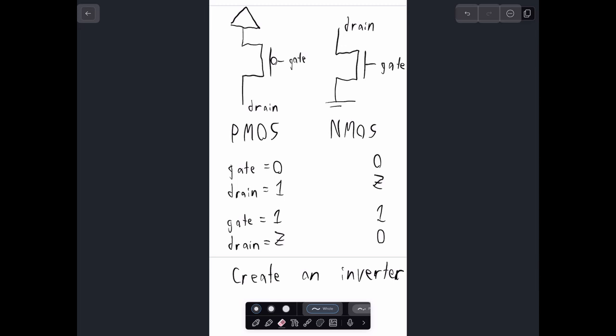Yeah, question. The power is only used for switching. Exactly. But it takes some charge still to charge up all your wires, and to change the capacitances within your transistors. So you only have switching power in CMOS, which makes it extremely power efficient. And this is why it has driven modern day technology.